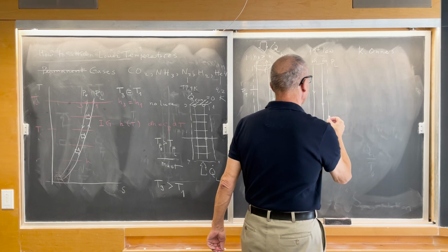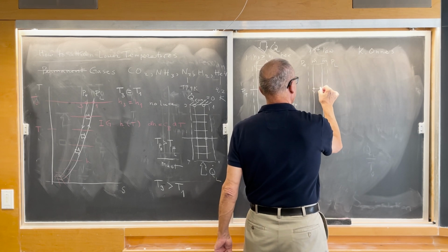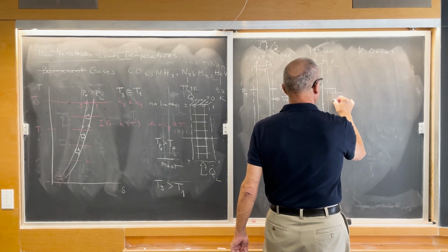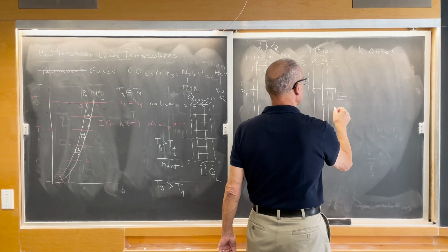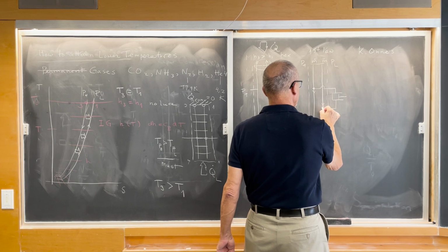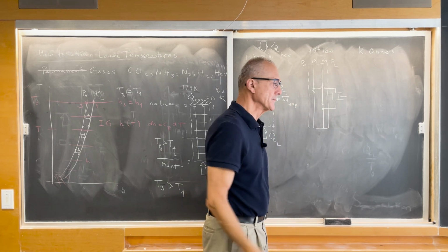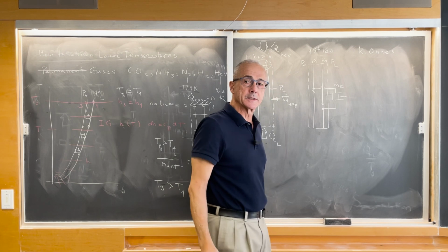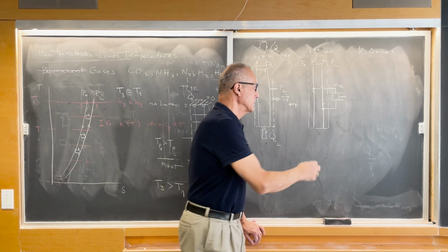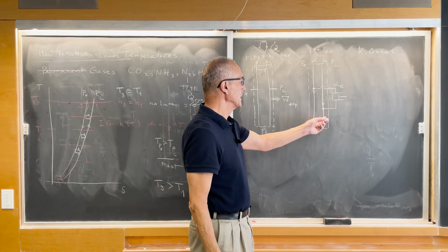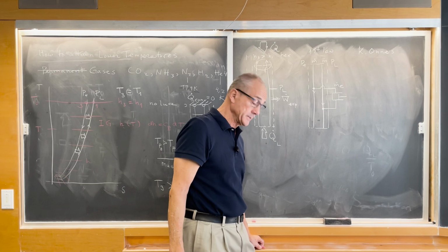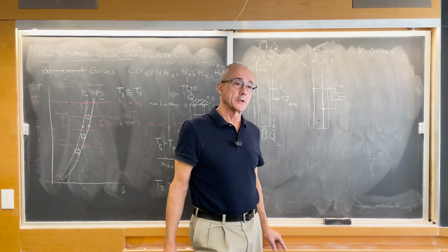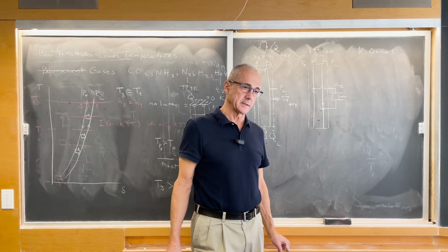The technique is to bleed a fraction of the high pressure stream and to expand it through a cylinder and piston apparatus, and then to dump the expanded mini stream, let's call it m dot E, which is the fraction that flows through the expander, into the low pressure stream at a lower temperature, because that is what happens to an ideal gas during close to reversible and adiabatic expansion.